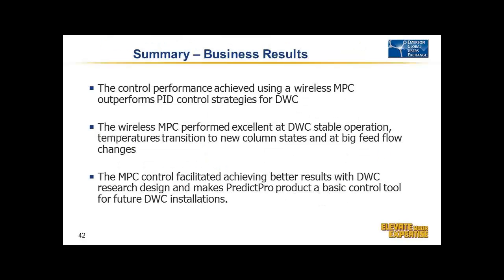So in summary, we were able to achieve wireless MPC. We actually prefer to use MPC over PID while operating the pilot column. Wireless performed excellently. You can see the stable temperatures with the wireless MPC. And Predict Pro was able to help us, since this was a hydrocarbon system we used in May.